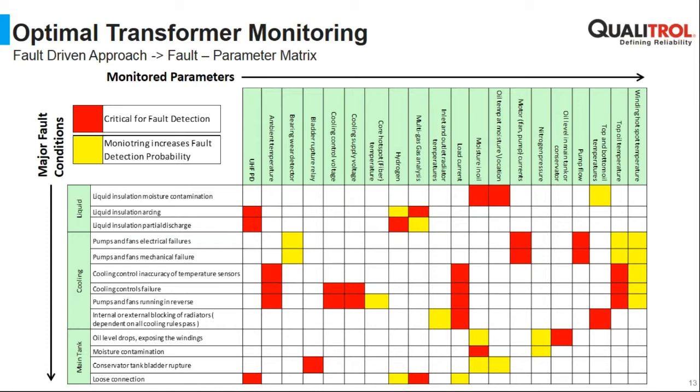So in order to find out some failure in the pumps and vents, you need to measure the motor current, for example, and you should measure also the flow. So in that regard, you are sure that first of all motors running, and second that you also know that the oil is flowing, which is important for just getting a cooling.